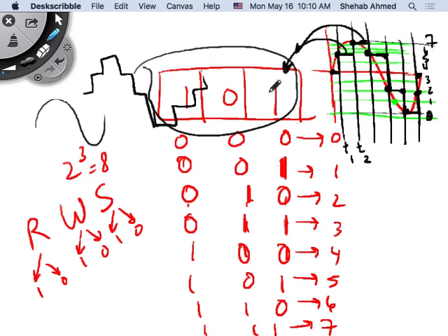If I increase the number of bits, what's going to happen to my sine wave? It will look more like a sine wave. So the higher the number of bits, the less information you lose, right? And the higher the frequency of sampling, the less information you lose. Because remember, every time you sample, you will quantize the signal, meaning between one sample and the next, the signal will be the same value, right? So you still lose some information. Even if you have a lot of bits, you still lose some information, right?